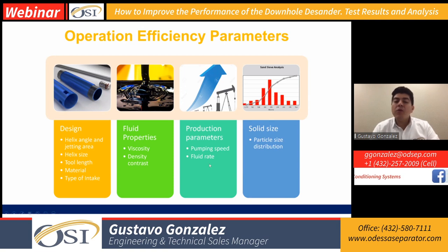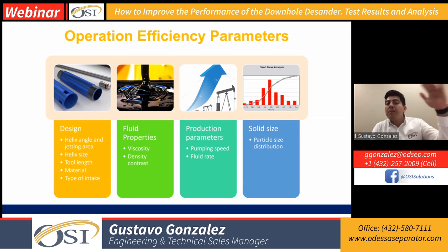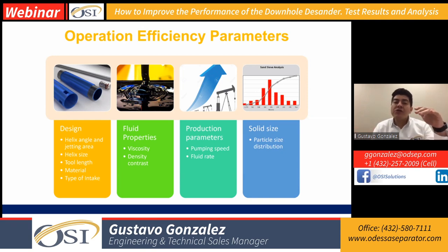Another thing that is important, more in unconventional wells, as you described at the beginning, is that we see different peaks. We see production that starts maybe at 4,000, getting a peak, maybe my child well is affecting, and now my parent well, due to the pressure, is sending some of the fluid to my shorter well, and I see a peak, and now my well is lifting 7,000 barrels per day and is declining in less than a month to 3,000.